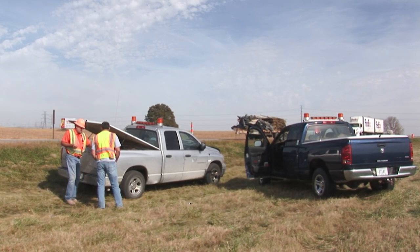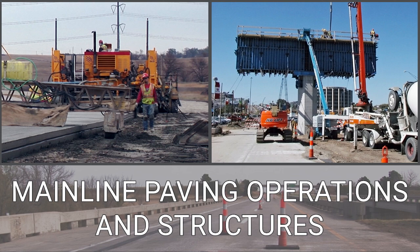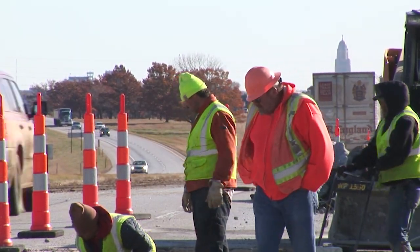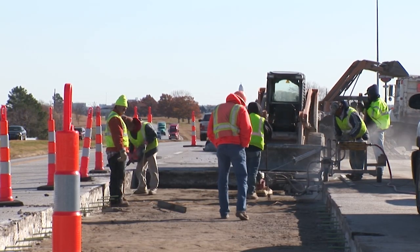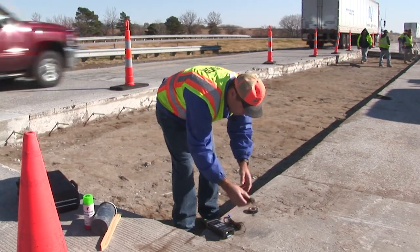2 maturity installation applications will be presented in this training. One application will cover pavement repairs and miscellaneous placements, and the second application will cover mainline paving operations and structures. The first step is to determine where the thermocouple wires and connectors will be placed. It is recommended that you place your wires at the beginning of the day's placement. It is suggested to set up as far away from traffic and construction equipment as possible.